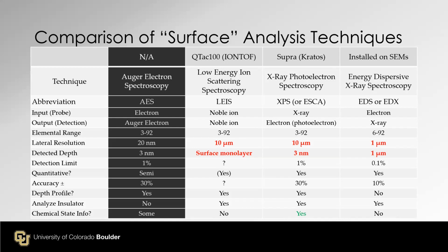The biggest disadvantage of this technique, in my opinion, I asked the XPS application specialist as well, is it cannot deal with insulator analysis. Chemical state information, binding state information, maybe, but there is a limitation. So insulator, it works great for conductors, but not so much.